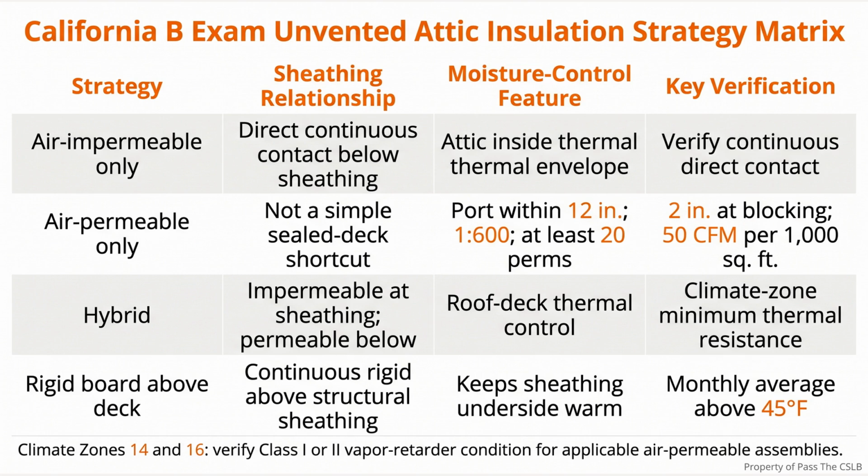I treat that as a planning issue before framing is locked in. The access location has to work with trusses, ceiling framing, ducts, electrical work, insulation, and the future service path. A minimum opening that cannot serve the installed equipment is not practical coordination.